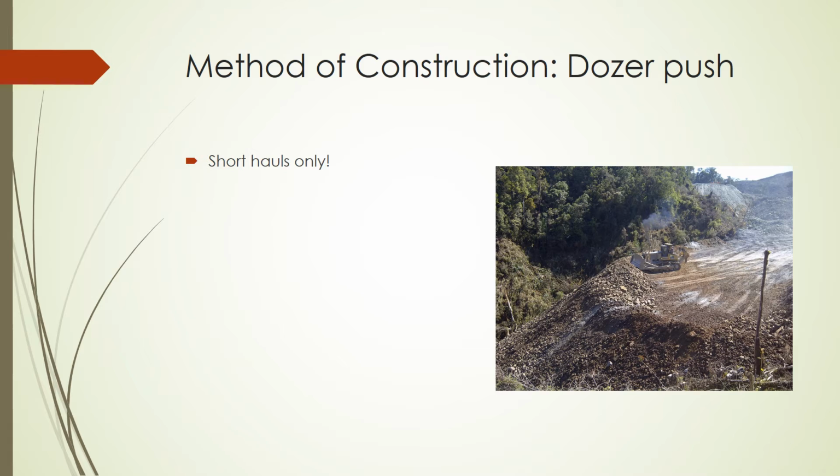And last but not least, and it's certainly an interesting one, is a dozer push construction method. Now, this is a very short method of construction. Typically, it's most effective in a transverse cut and fill scenario where we've got a cutting and we use the dozer to dig into the face and push into the fill slope. That's what you're seeing with this dozer in the picture right there. And it's a good system, but once you've exhausted your short fill, it really becomes a case of